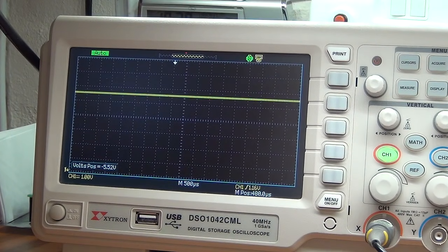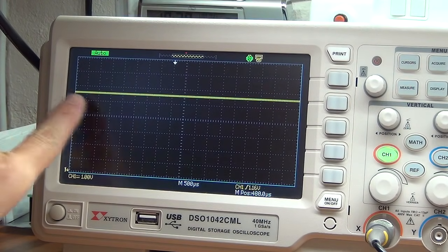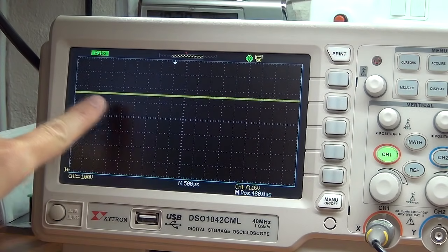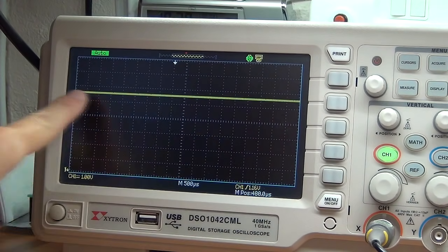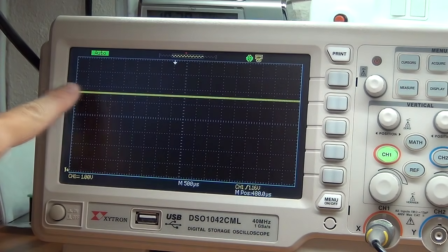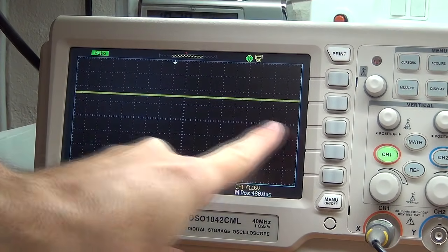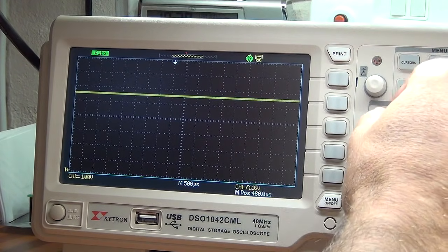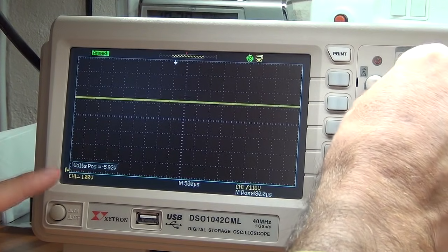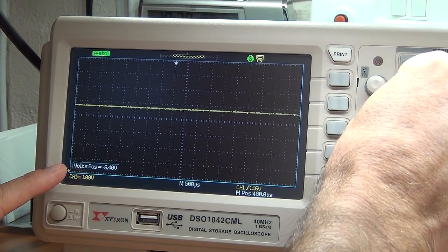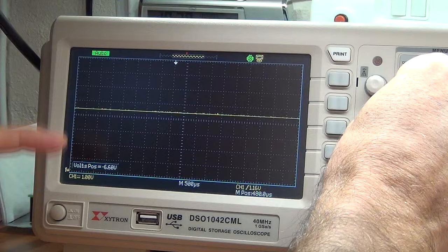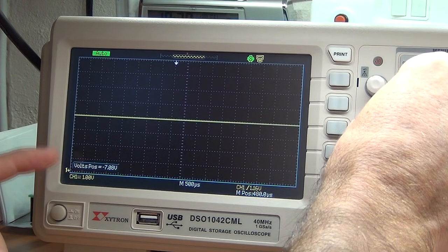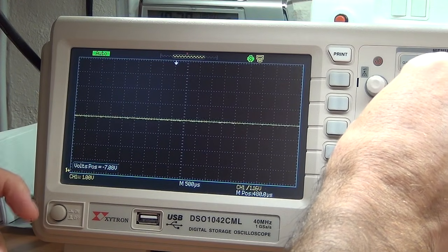And as I showed you on that diagram, this is what a multimeter would perfectly represent as a reading if you put it across that battery. It's a straight line because the value is not changing, so it's simply a straight trace across the screen. Now as I bring that down, you'll see there's a volts position, and it's showing negative because in essence the 0 point is being moved down as I'm adjusting the vertical position.